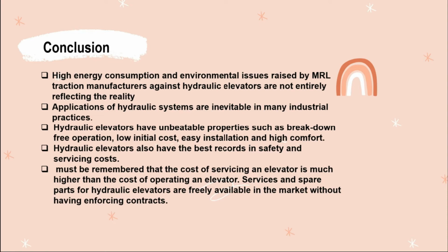So, for the conclusion, the high energy consumption and environmental issues raised by MRL traction manufacturers against hydraulic elevators do not entirely reflect reality. Next, applications of hydraulic systems are inevitable in many industrial practices. Hydraulic elevators have unbeatable properties such as breakdown-free operation, low initial cost, easy installation, and high comfort. Hydraulic elevators also have the best records in safety and servicing costs. It must also be remembered that the cost of servicing an elevator is much higher than the cost of operating an elevator. Services and spare parts for hydraulic elevators are freely available in the market without enforcing contracts.